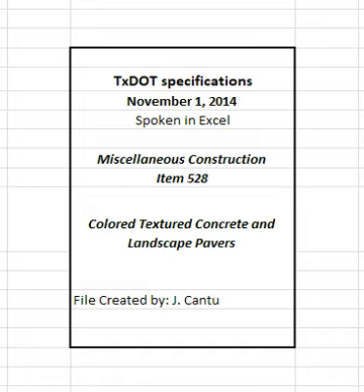1.3 Landscape pavers, furnished. Landscape pavers will be furnished by the department. Load and transport from the location shown on the plans to the project, and install. 1.4 Remove, store, and relay landscape pavers. Remove, store, and relay landscape pavers as shown on the plans or as directed. Furnish and lay replacement pavers.